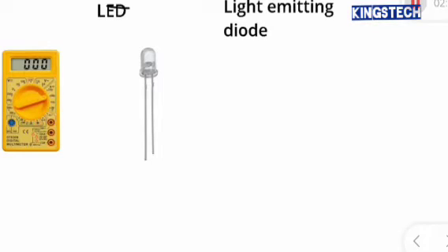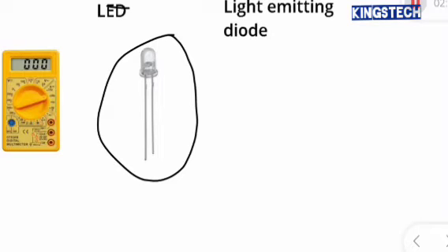If you look at this light emitting diode here, this LED, for example, you can identify the negative and positive from the legs, the terminals. If you look at this one, you find that this one is shorter than this one. The legs are not of the same length. This is the way they appear naturally. Any light emitting diode you pick up, its two terminals cannot be of the same length.